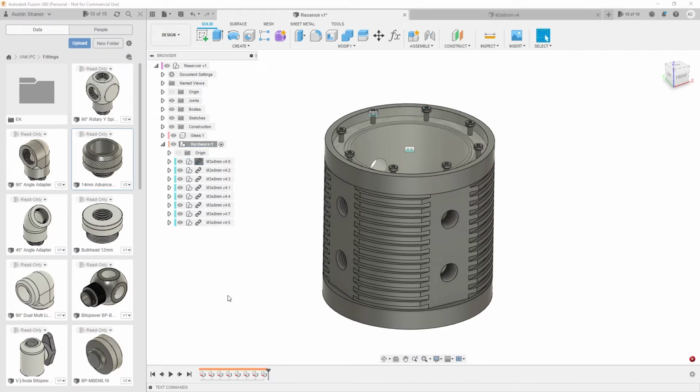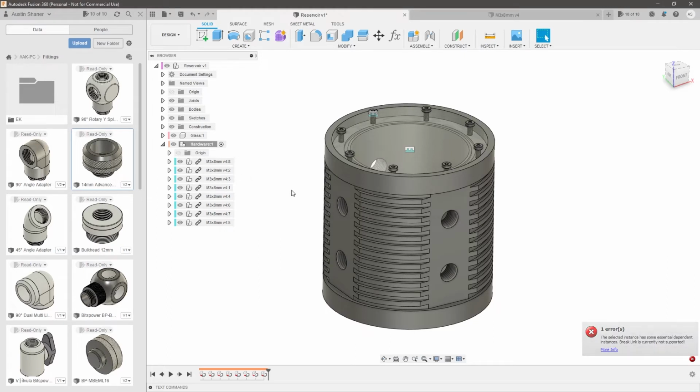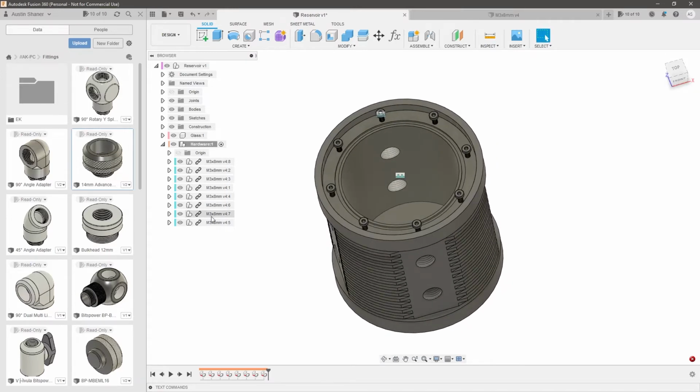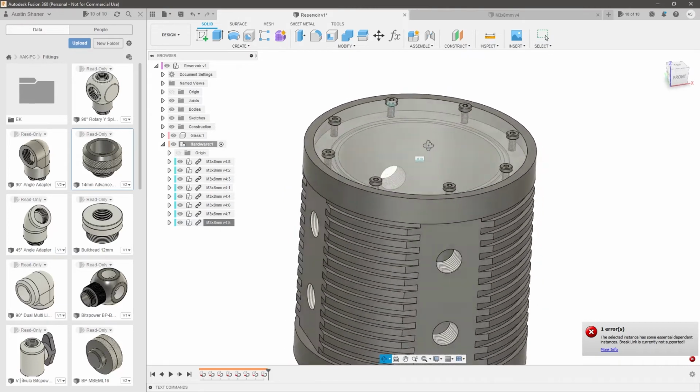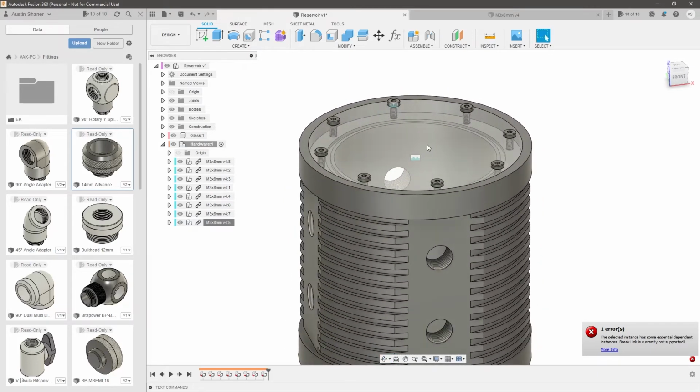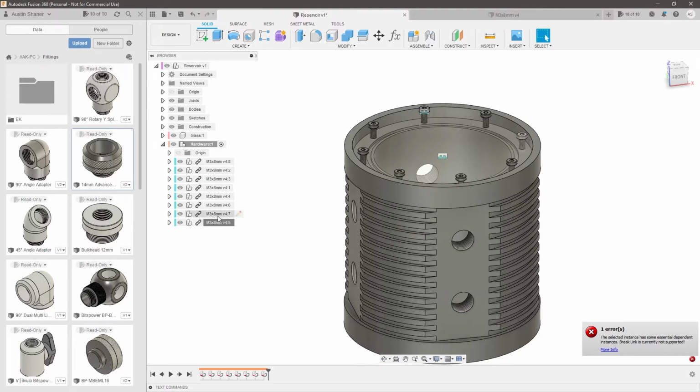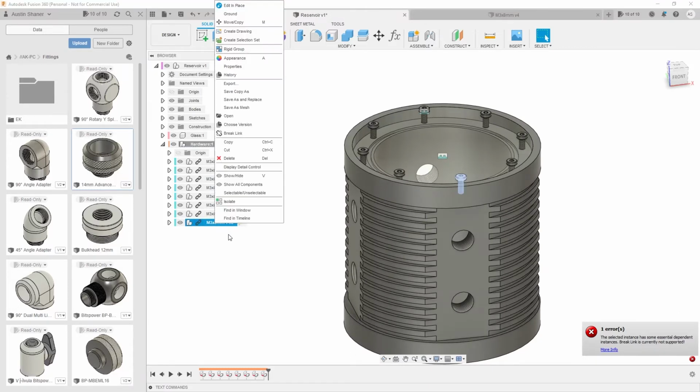And what that means is if I break the link of that individual part, let's see here, it didn't want to break that. That might be because that is the top one. Let's try this. Break link. Okay, it's not letting me do that because it's a circular reference, or not a circular reference, but a circular pattern.